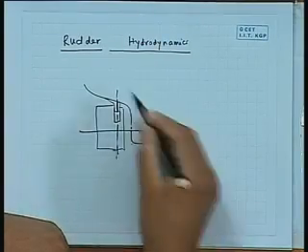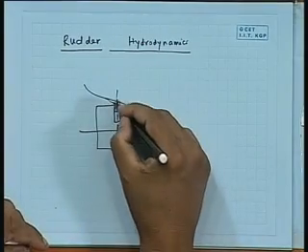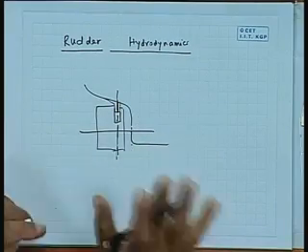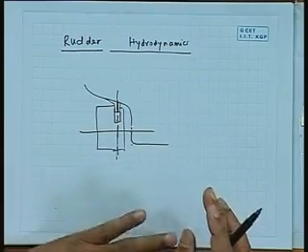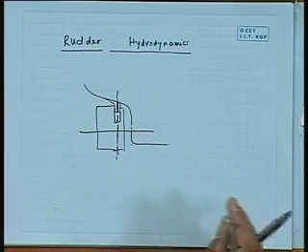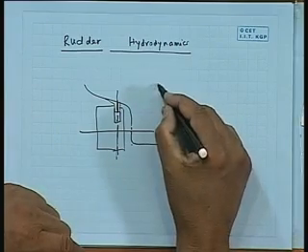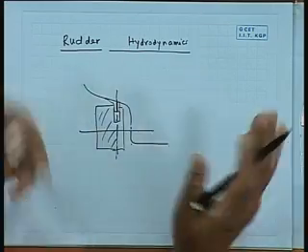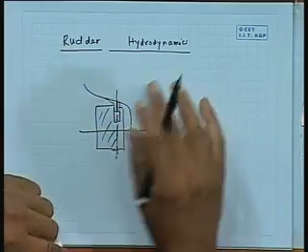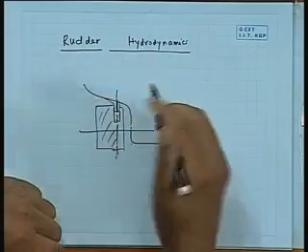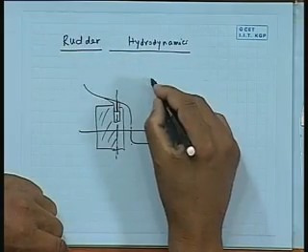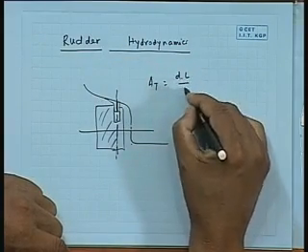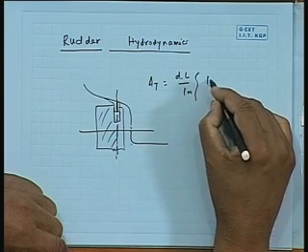So if you take a rudder here, something like that, it has got a rudder stock. It might have earlier had a rudder post, but as I said, I am not getting into the detail of the construction part of rudder. In fact, there used to be an empirical formula about the rudder area also, how much it should be. It turns out approximately 2% of the central plane area, or some other empirical type formulas, d into L by 100, something like that.